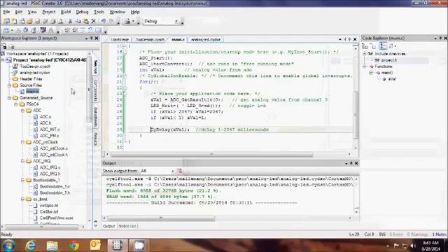Yeah, it works. The only thing is the speed is wrong. The 1 millisecond delay at the one end of the pot is just too fast, and the 2-second delay per flash is too slow. So I'm going to scale my analog input. A little more difficult than Arduino.